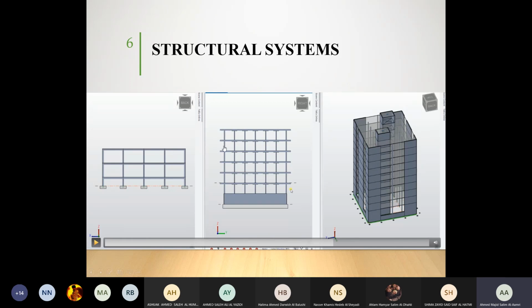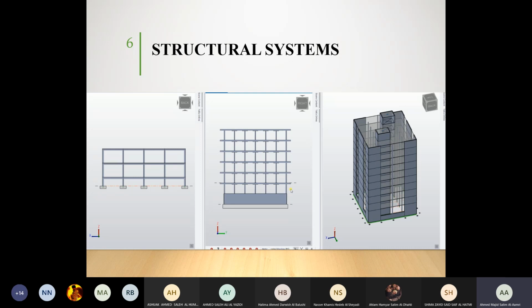So normally for residential and commercial buildings in Oman, we are using a lot of flat slab system. So either flat slab, if it's like 3 stories and above, or residential commercial, normally we prefer to go for flat slab, either fully flat on columns, or whatever is used mainly, which is flat slab plus columns and core wall, which is the last option.